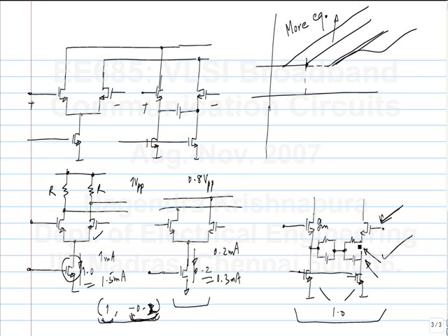Here we don't need them. So that's the difference. So that's what I was saying. In the case of this equalizer, the continuous time equalizer, all I need to do is take the high speed binary bit stream and feed it to these inputs. Whereas this circuit is not complete. I need two flip-flops between the two, okay? And I need a clock that is driving that. All of those consume power.